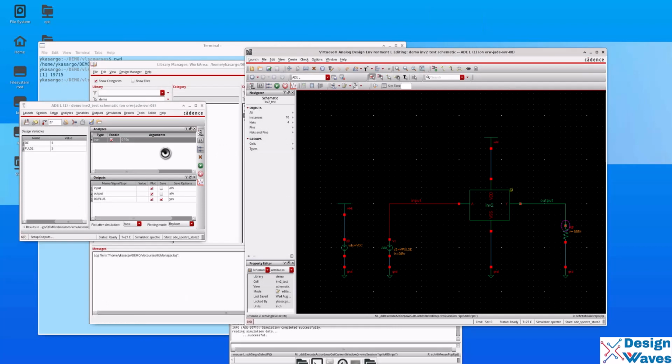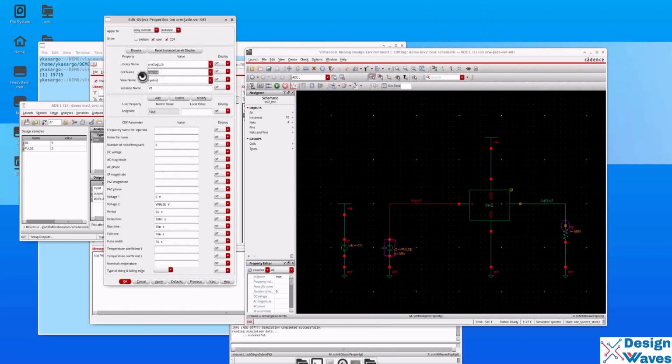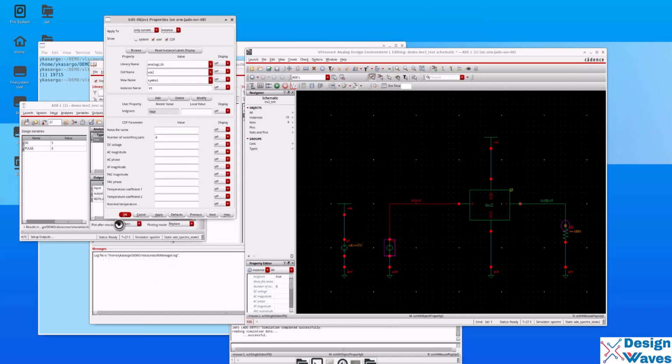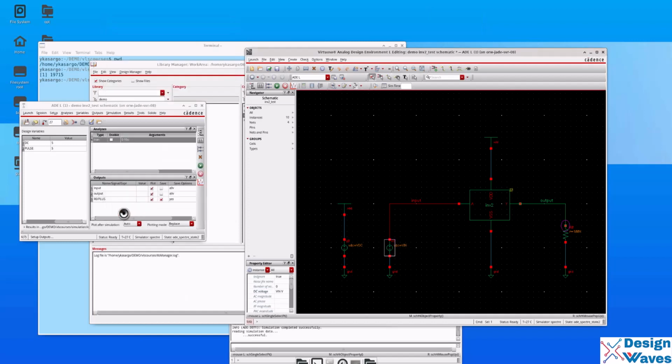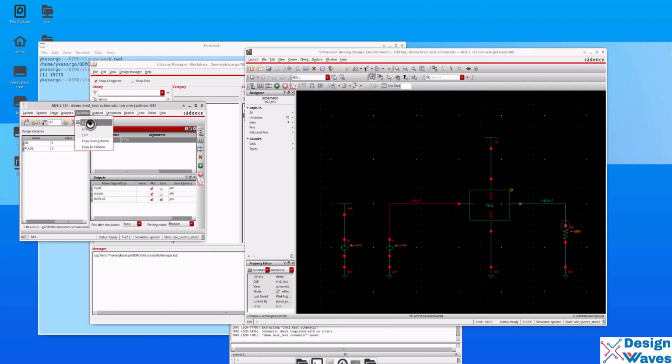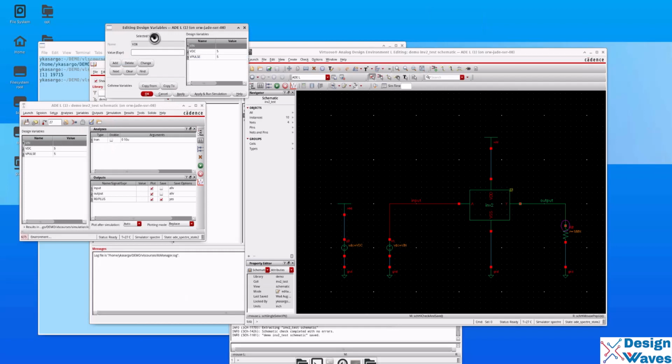Now we will find out the DC characteristics. We will find out what the DC noise margin is. For this we have to change this one to VDC, click apply, and the DC voltage we can make Vin, right? Okay, Vin. Then you can save. Then go to variables, copy from save view. Vin we will make 5 volts for the time being.